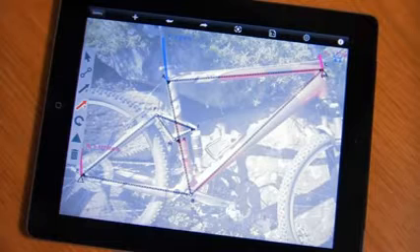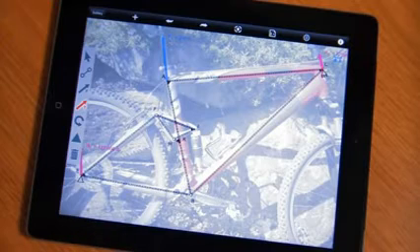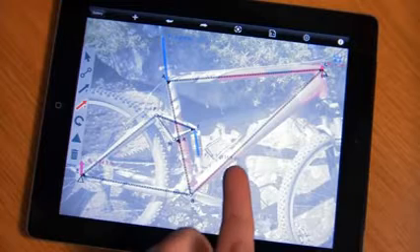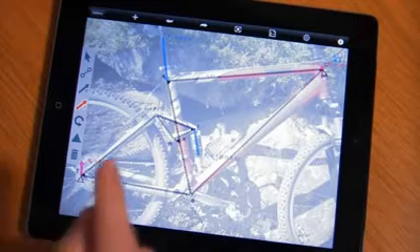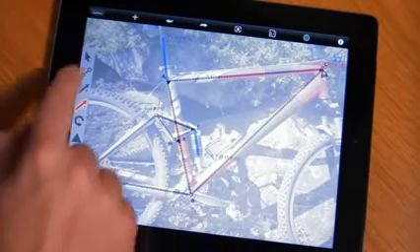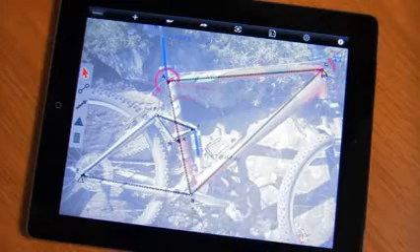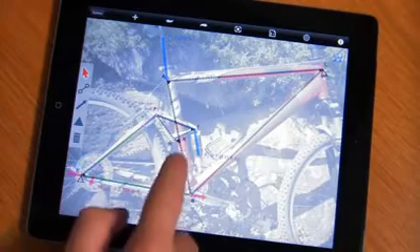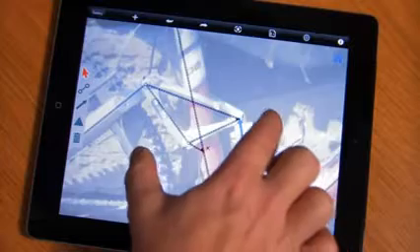Now that we can see our forces, we have another innovative solution here which allows you to put in an unknown force at any point in the system, and we'll back solve for equilibrium to give you the reaction at that point. That's a perfect tool for this particular problem because we can ask for the unknown force across this piston. Notice the system automatically solves for it and tells us what the reaction will be there given the setup and load that we have. Now at this point we can go in and start looking at each of the reactions across the members, isolating those, or we can go in and start actually iterating on our design.